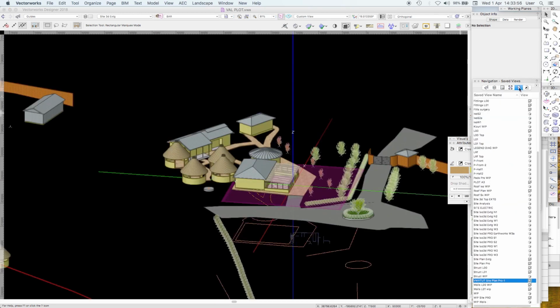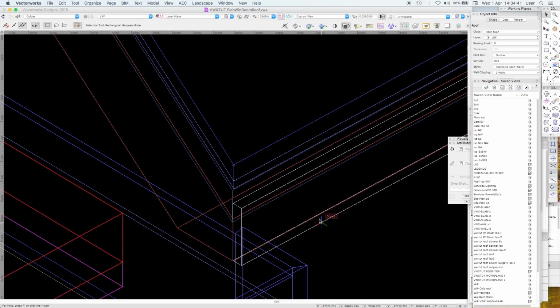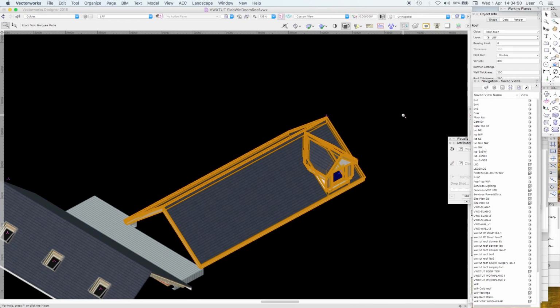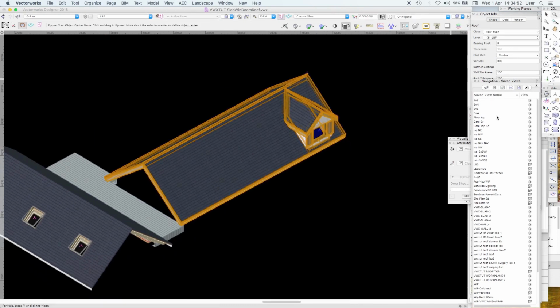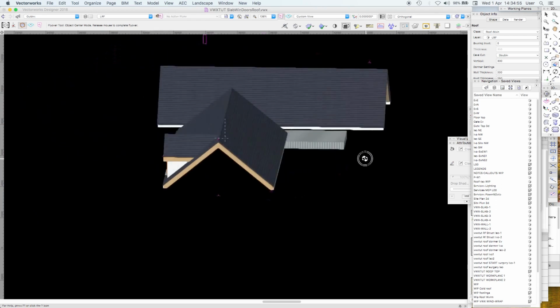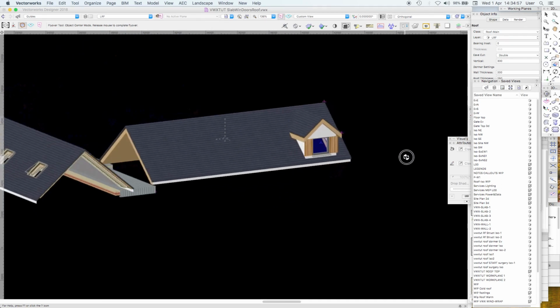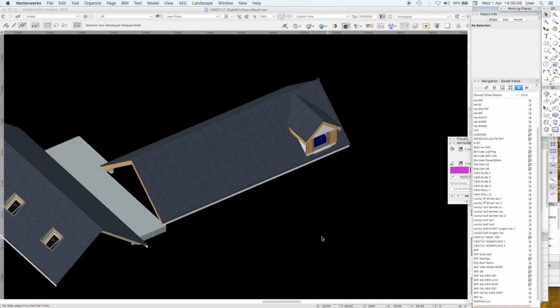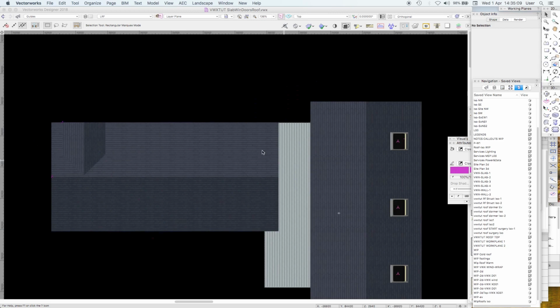So that's its usefulness on a site plan, especially modelling the existing, which you want to do quickly with massing models. The second and perhaps more obvious use of the working plane tool is in planes that are not orthogonal to the top plan view, particularly roof pitches. If you want to see the true elevation of that roof, obviously looking down on it, when we try to measure it, it's not. That isn't its surface, is it?